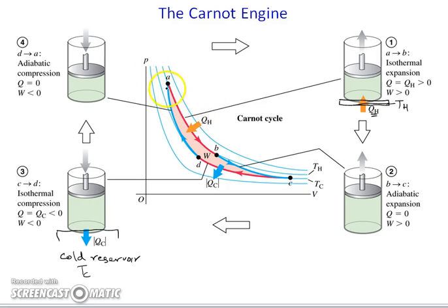During this cycle from A to B, positive work is done by the gas, and from B to C another positive work is done. So from A to B and B to C, positive work is done by the gas in expanding. If there is some load on the piston here, that piston will move because of this work. If you want to know how much work is done, we can calculate the area under the curve ABC.